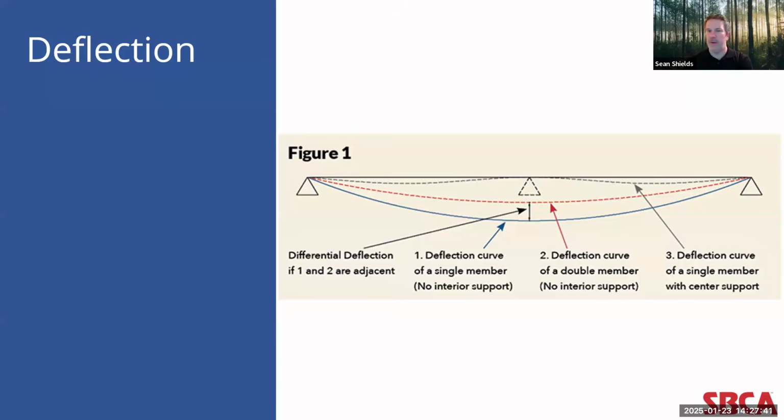Another section that the building designer is going to want to pay close attention to is the deflection section of the truss design drawing. Now, deflection measures how much the truss will move out of plane when under load, which includes both live and dead loads.